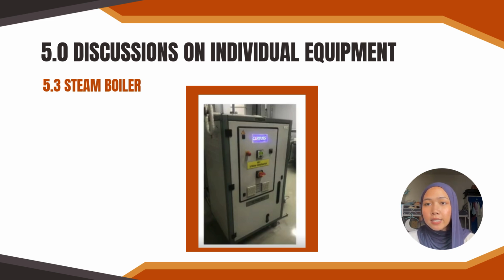In an ethylene oxide sterilization plant, the steam boiler converts treated water into high quality steam for humidification and heating. Steam quality is critical. Saturated steam provides efficient heat transfer and moisture to activate the ethylene oxide gas. Superheated steam is avoided as it behaves like dry gas and reduces effectiveness. Clean steam produced from high purity water in stainless steel boilers ensures safe, reliable, and effective sterilization.